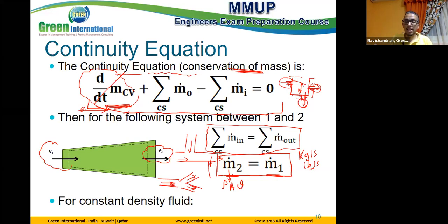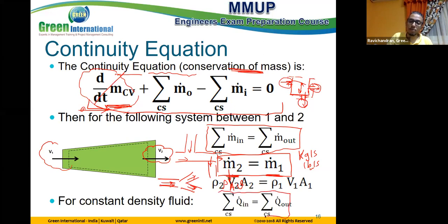And in this case, we will find AV equal AV, which represents Q. And what is Q? Volume flow rate. It's more famous and more used in the exam than m dot. Sometimes we use m dot, but normally we use m dot in case the flow is gas, which has a density change. For incompressible flow, we use Q in equal Q out, which is AV equal AV.